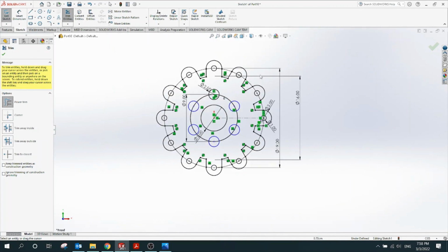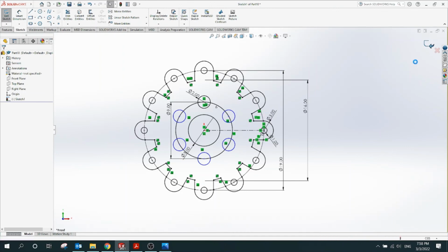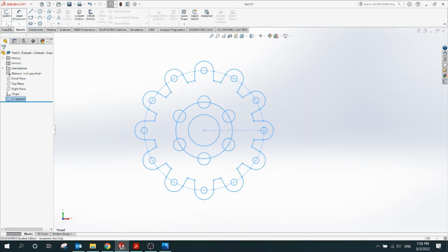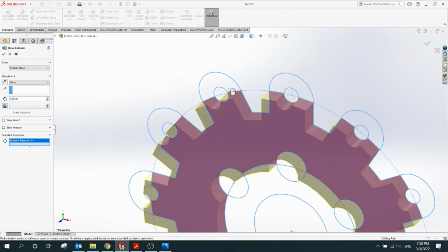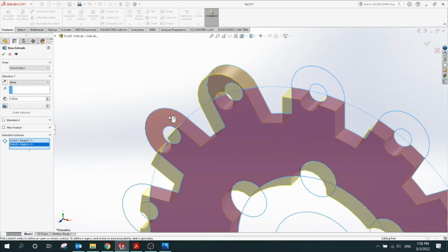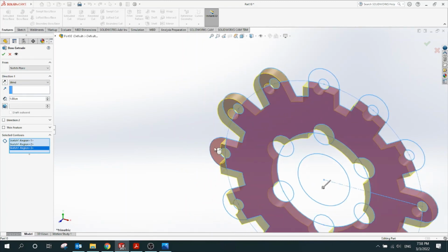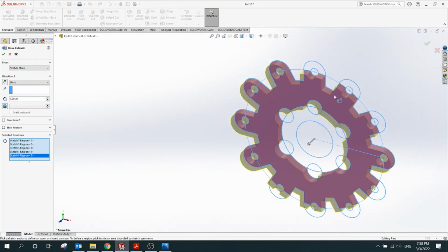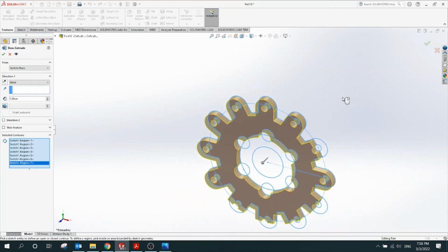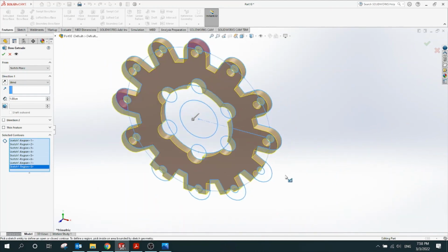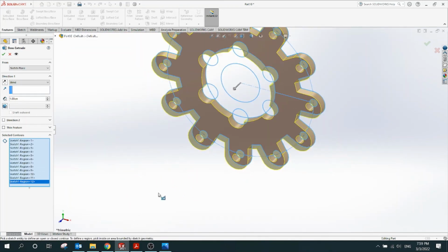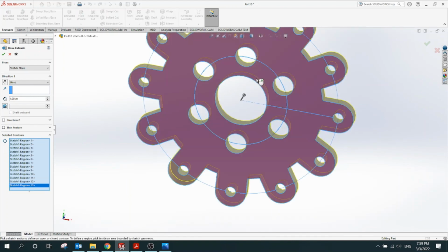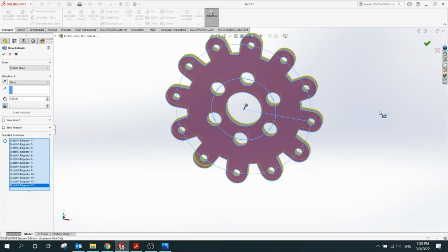And that's it. So this is my drawing, and if I finish the sketch, I can extrude the object, but I have to select all the contours that I need. For example, these small segments, and this is a kind of gear system or maybe a gasket for any mechanical component. So I would select the spaces needed to be filled with material while leaving the other elements empty, and finish. And that's it.